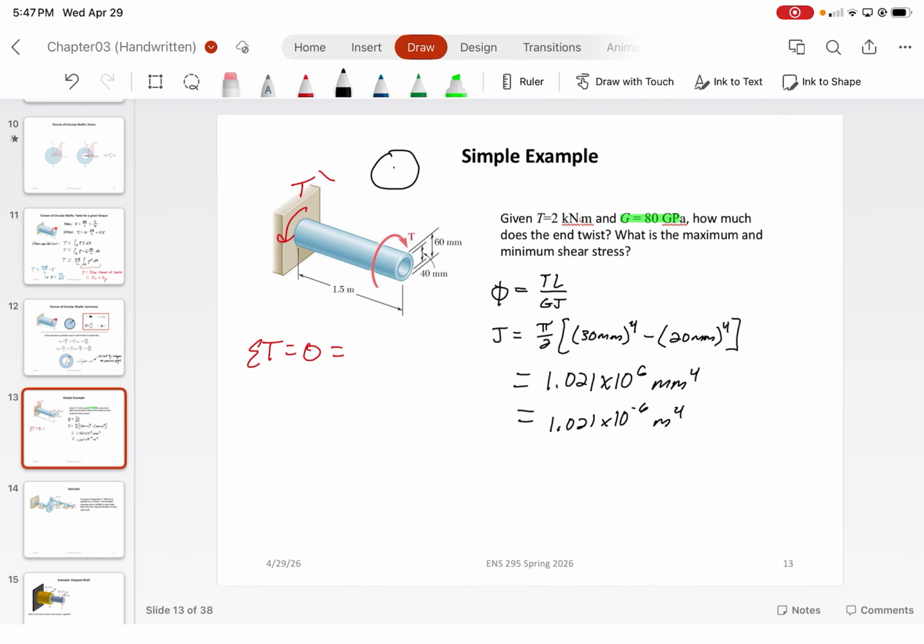In this case, if we look at the circular shaft here, and we look at the rotation that T is causing, is that a positive or a negative torque? Negative, all right? It's ultimately up to you guys to assign the sign conventions, just indicate whether it's counterclockwise or clockwise at the end of the problem, all right? So we're gonna have -2 kilonewton meters, and then we add that to T prime, assuming that it goes the opposite direction or counterclockwise, and we get that T prime is just equal to 2 kilonewton meters clockwise.